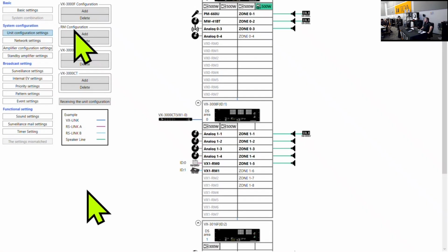Yeah, because we were talking about this earlier, about making it redundant. So maintenance, a frame goes down. Now I've got to send somebody with a laptop and everything else to go out there and re-push the configuration to that dead frame. If each frame had a full copy of the program, I could say, okay, take the program from the first frames, and when I put the new unit in, on boot up, it would check to see if the stuff is there. If not, it would then upload it to that frame. So basically I could have Joe Schmo or whatever put that in that rack, done.